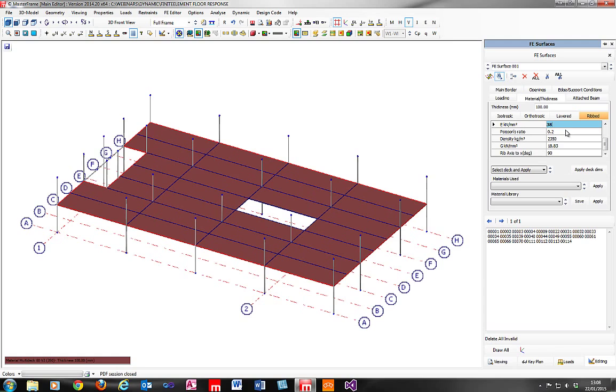Typically for concrete, for standard structural analysis for static design, you might expect to see a Young's modulus value of around 24. However, interestingly, and actually for all things modeling orientated, I would recommend that you look at section 6.1.1 of the SCI P354, which discusses a range of modeling issues, such as the value of the Young's modulus to use, and so that experiences an increased value for this dynamic state that we're looking at, of 38.